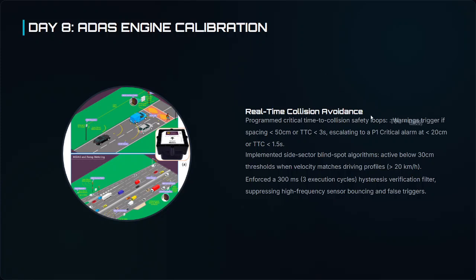If the distance read from the ultrasonic sensor is less than 30 centimeters, the time to collision is very critical, and it returns a critical indication with a warning on the dashboard and also a blinking red LED, which we will be seeing on the dashboard later.